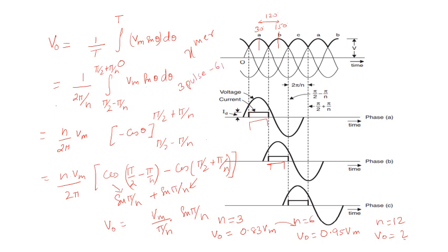The disadvantage of this square wave made us use at minimum 6 pulse, or 12 pulse or 24 pulse. You can use a converter above 3 pulse, but not a 3 pulse converter. It made us limited because of this waveform.